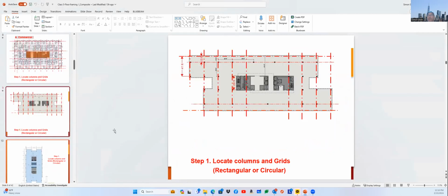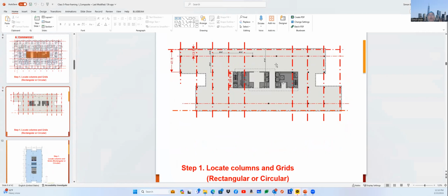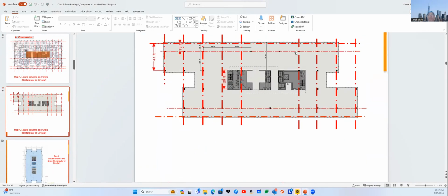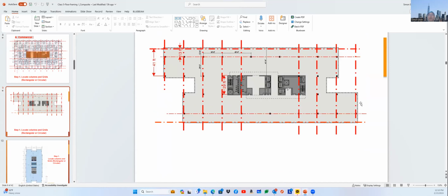Okay, now second. Some background. Not much extra background, but here, this layout: the building has a central concrete core layout, but again, two egress stairs are a must, right? But the number of elevators, passenger and freight elevators, is to be based upon your own vertical circulation requirement.